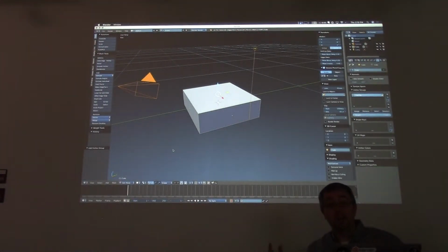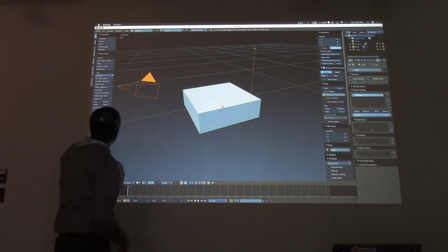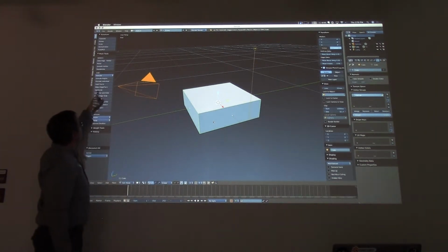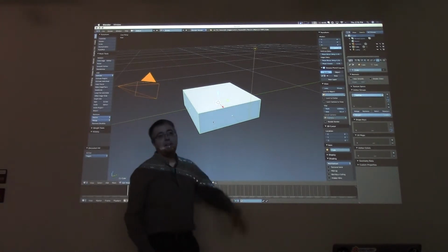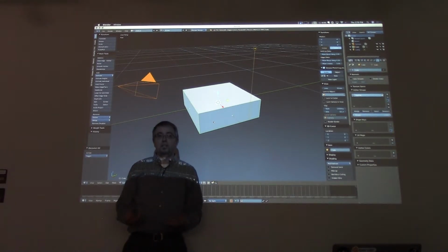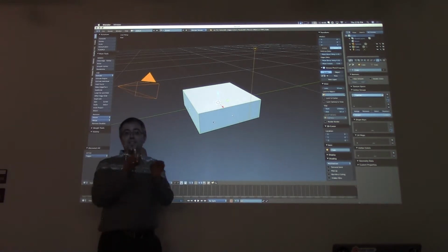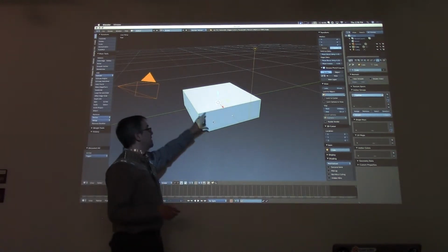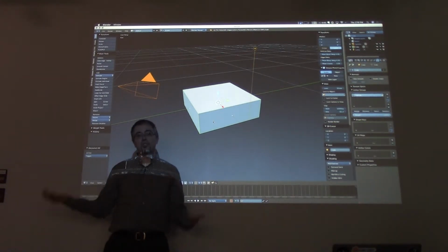Now we are going to cut up the object. And this is kind of interesting. So I can deselect or reselect, whatever. This is kind of an interesting process because there is a button called Subdivide, right? Here in my tools section. And the Subdivide button will subdivide every face on the object sort of in half. And then it'll do in half again, and in half again, and in half again. And that will actually look great on the top and the bottom. It'll make this into proportional squares. But on the sides, it means that we're going to have a whole bunch of stuff that we don't need. It's a whole bunch of extra geometry.